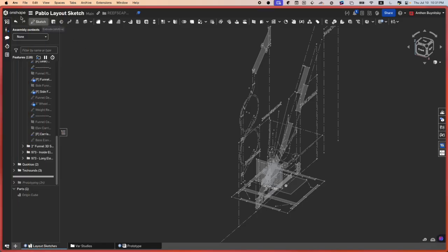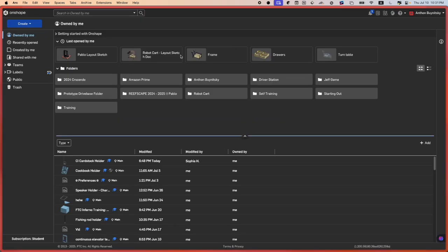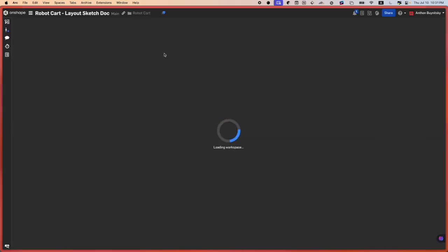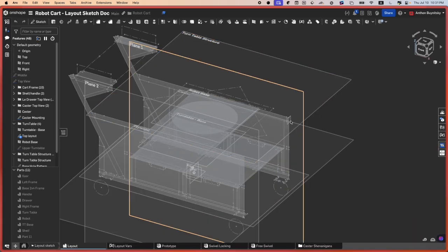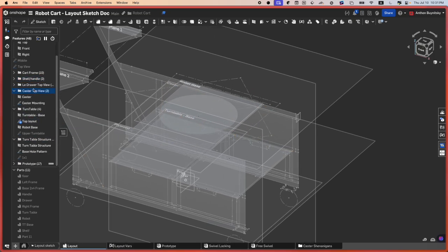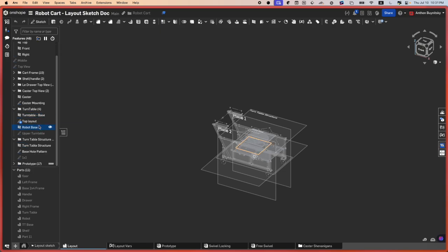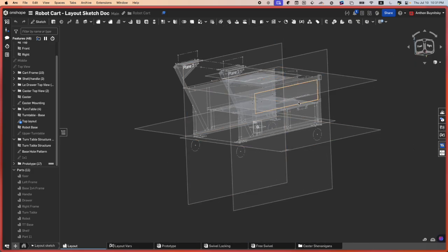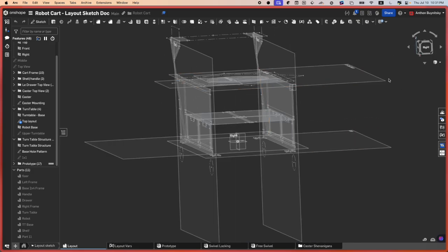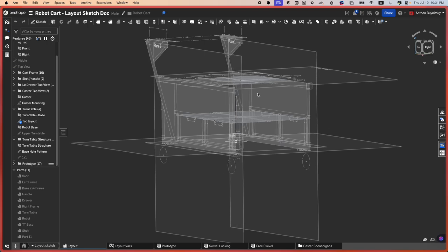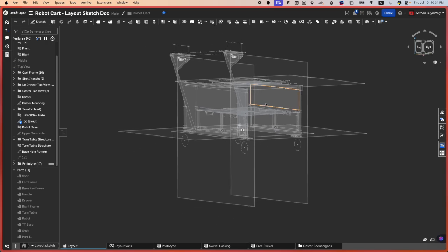So if we go back to the drive or the robot cart, you'll see that we did a lot of this, right? I don't know how many planes we made for this robot cart, but I see at least 4 right now without these folders being opened. So yes, the plane feature is definitely going to be another tool being used by you guys.